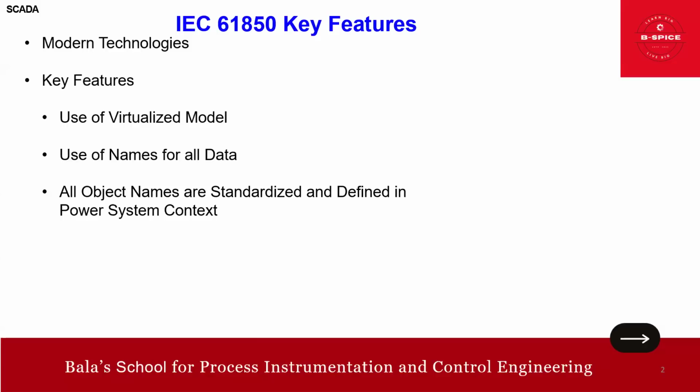Then the devices are self-describing. Client applications that communicate with IEC 61850 devices are able to download the description of all data supported by the device, from the device, without any manual configuration. So basically, these are self-describing. Then high-level services. As I highlighted earlier, it supports a variety of services like GOOSE, GSSE, SMV, just a few unique capabilities.